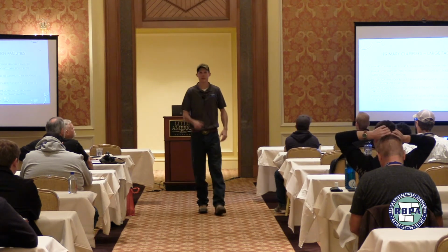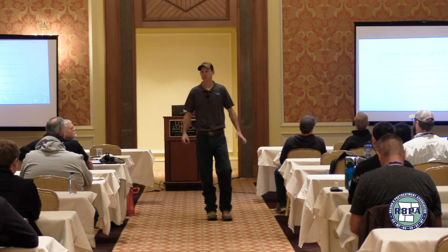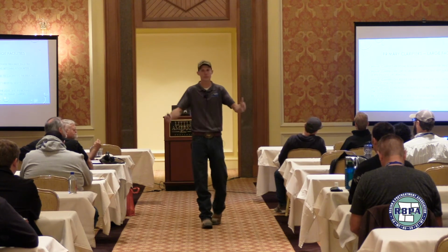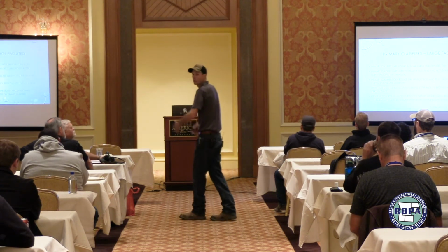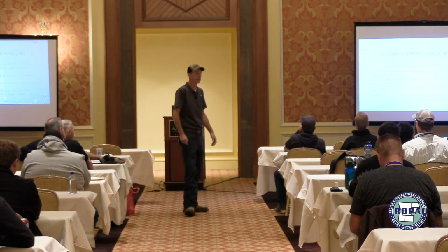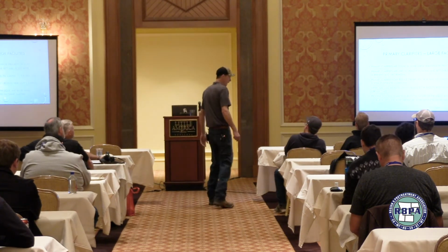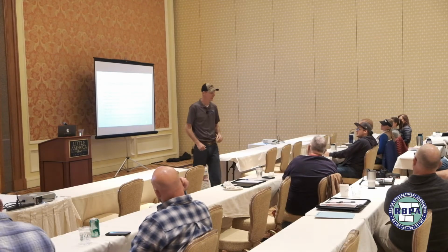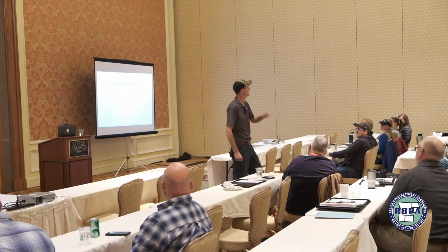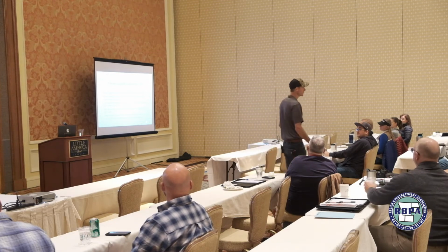Bingo. Everybody hear that? Offset your high flow periods. Basically, all your flow runs into a tank so that you don't get these weird influxes and surges of flow coming through your plant. Now, if I have an EQ tank at Longmont, they just put in a new EQ tank here a few years ago. I think it's a 2.5 million gallon tank for a 12 MGD facility.